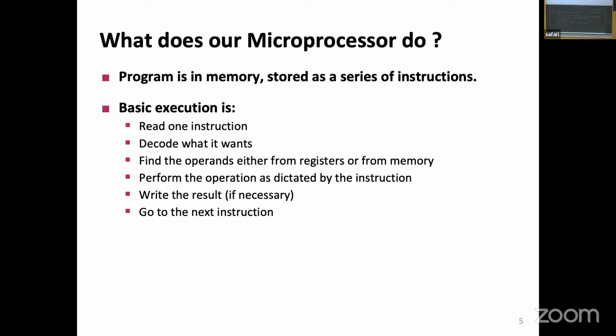Somewhere we will have a register that holds the program counter. Now, this program counter is going to go into a memory. There is an address, a 32-bit address that enters here, and corresponding to this address, there will be a data out that comes out, which contains the instruction that I'll be dealing with. So this is the data memory. And so far, this first part that I did does this part, right? I fetch an instruction. How do I fetch it?